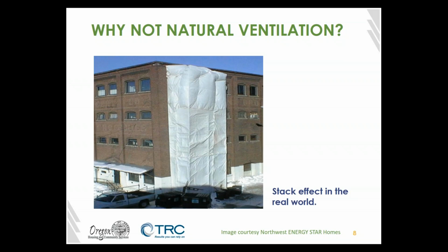So the stack effect, everyone says that stack effect drives natural ventilation frequently in some buildings, and that's true. Stack effect is a pressure differential where you have a different temperature, you have a different pressure on the bottom of the building than at the top of the building, being pushed against the building's facade itself because of the temperature dynamics on the inside. And so air naturally ventilates in from the bottom and out to the top to some level.